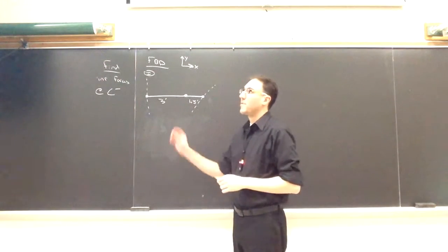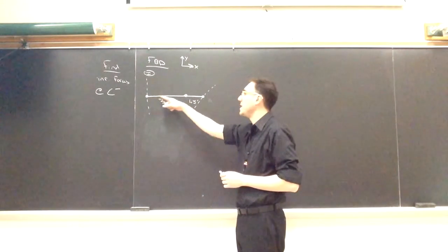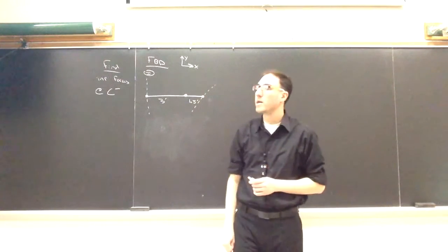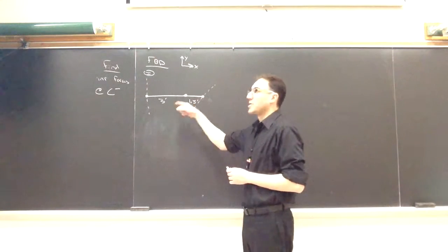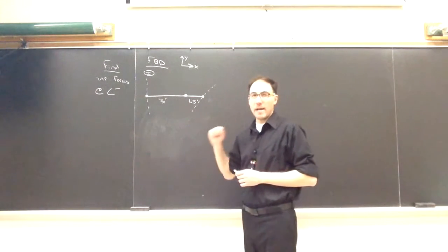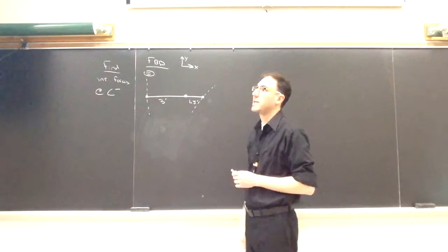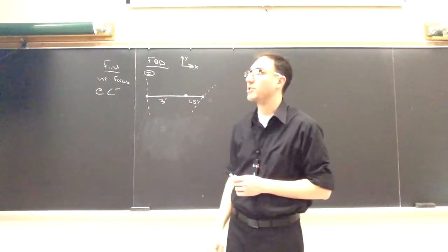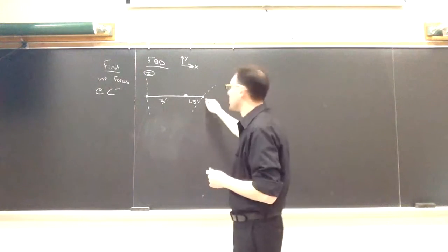All right, so if I simplify this beam that I'm isolating, I have the collar and then the beam, and then I'm taking away the rocker portion of it. So the blue pipe structure is my picture. I'll start here by looking at the external reactions. At D, where the collar is connected to that pipe, outside that pipe, I'll have reactions there. And where I remove the rocker, I will also have reactions. So let's start at B.